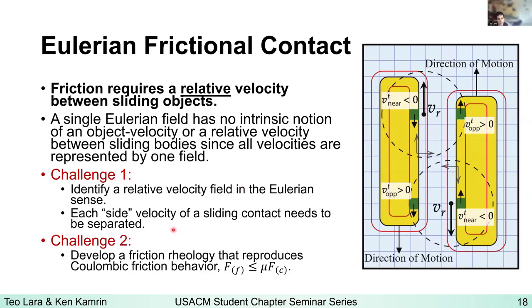And then you also need to develop a frictional rheology that develops the Coulombic friction behavior. So the friction force should be less than or equal to this coefficient of friction times the contact force, reproducing both the sticking regime and the sliding regime for your frictional contacts.